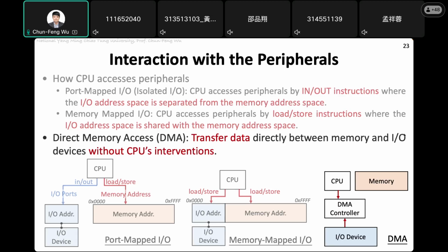Sorry, I have a question. DRAM is volatile, right? So after we see the translation, there will be multiple NAND chips. When you power off the DRAM, the DRAM translation table will have a version on the NAND chips. Yes, when you power off the SSD, the translation table from the NAND chips is first moved back to the DRAM when power returns.